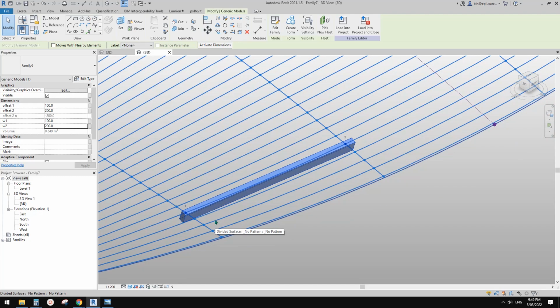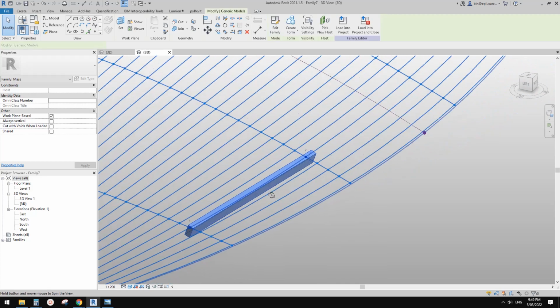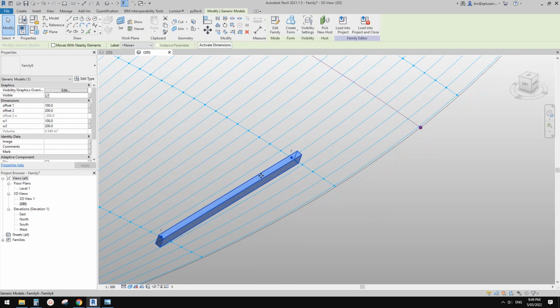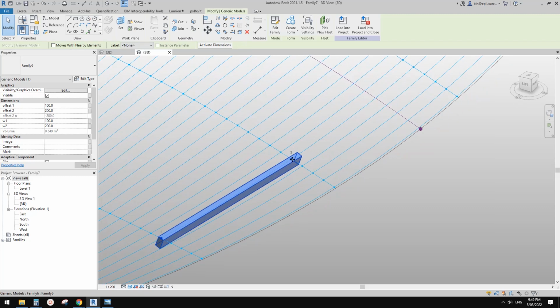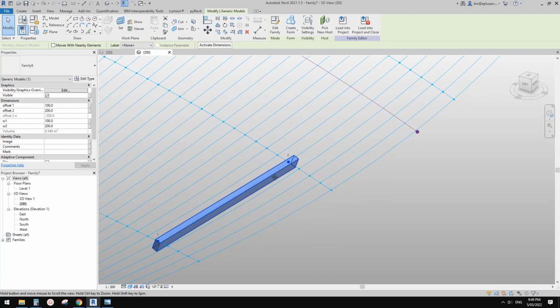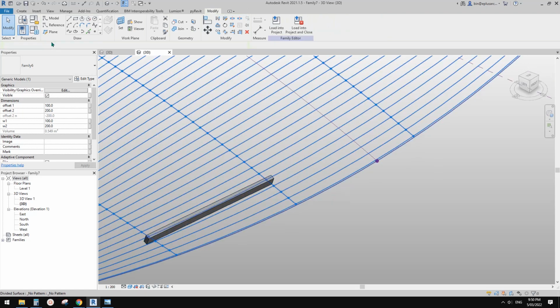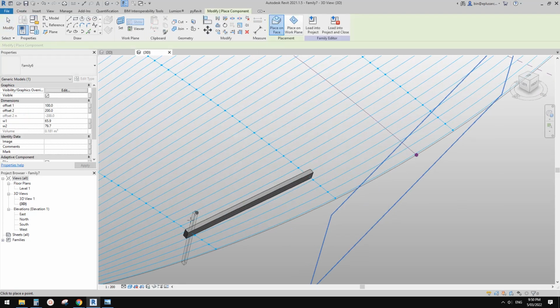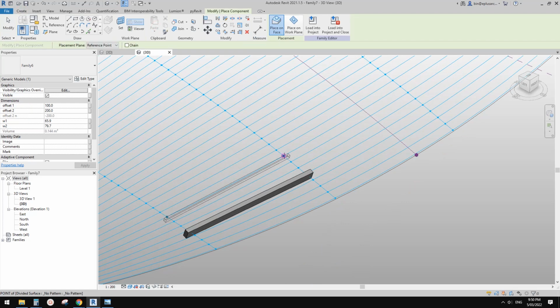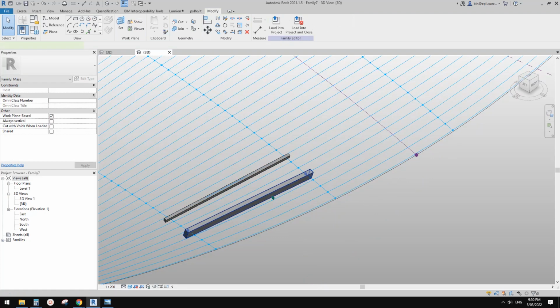Okay, so you have two options to adjust which side you want to offset. One is to add a rotation angle parameter into this family. The other method is, when you place this one, if you create a component in this direction, you will see it's on your right. So let me just match property.